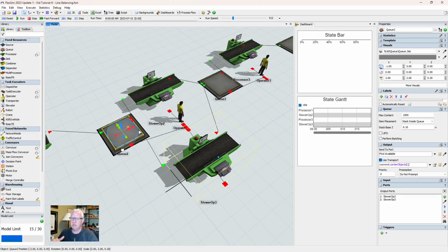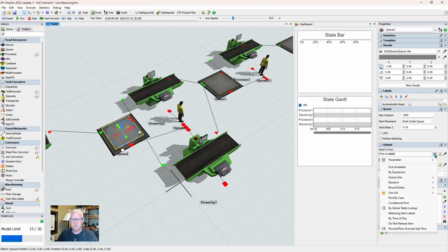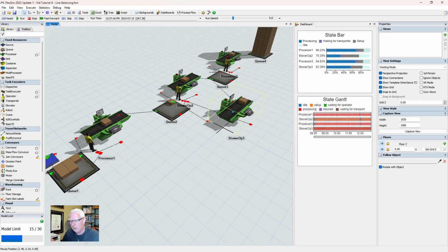So you could also get a real imbalance in machine utilization. I would argue if we've added a second machine here to run in parallel, even if they don't run at the same speeds, instead of sending to first available, having this logic by default, I would choose round robin, which means feed each of the outputs in turn. But now we've got a nice balance, at least, between the two machines. It's not favorably running on just one machine.